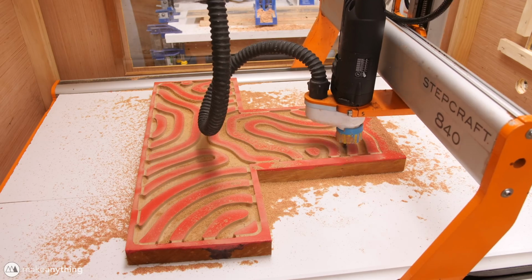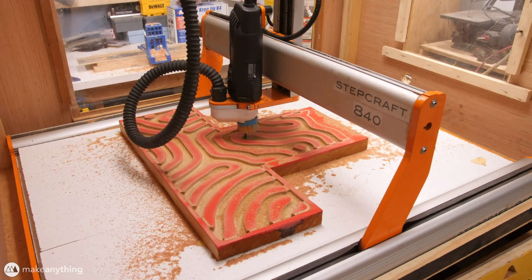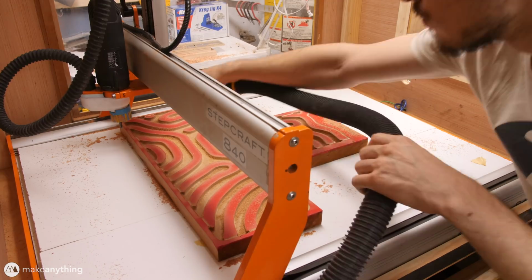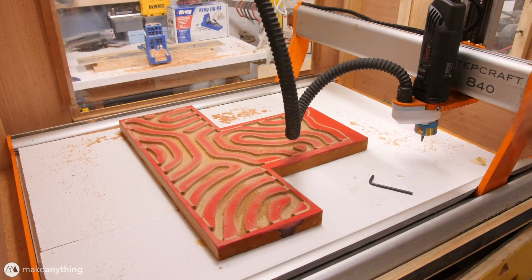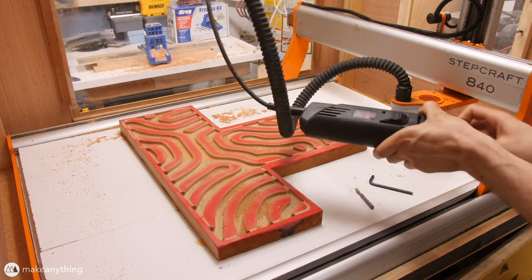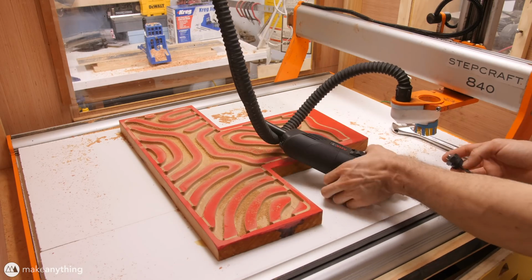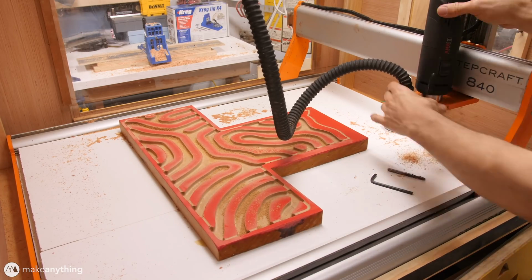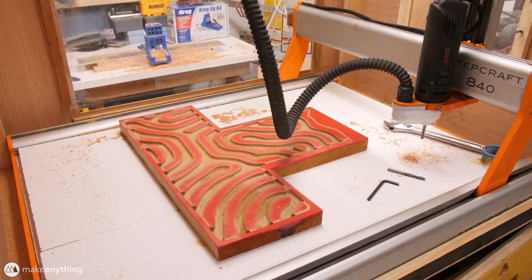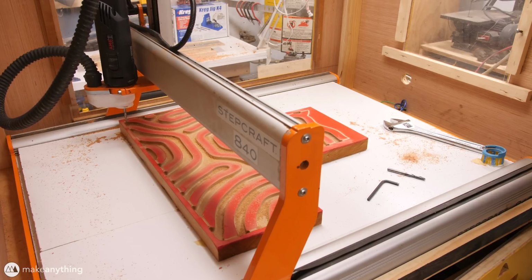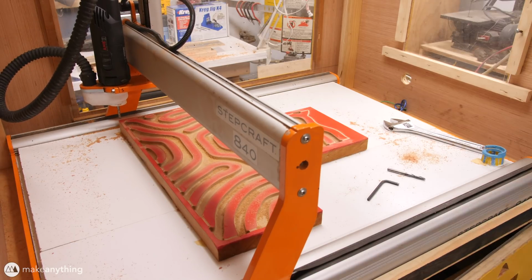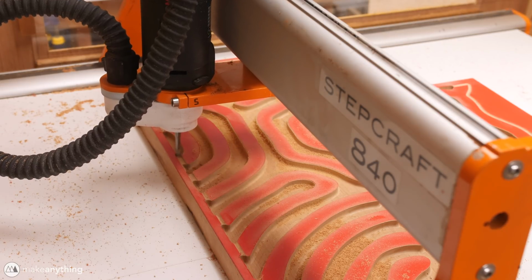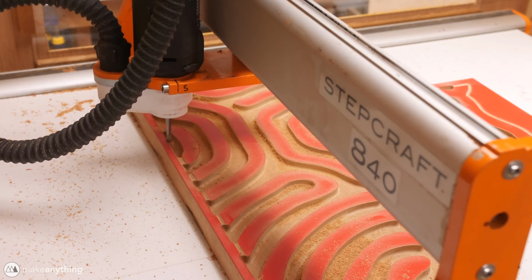Luckily, my Stepcraft 840 CNC completed all of the cuts with no problems. And then after a little bit of cleanup, I went ahead and switched out the tool bit manually. So I'm just gonna go ahead and pull it out, take out that flat end mill, replace it with the round end mill, and then make sure that the 0 position is still the same right in that corner. And then I'll run the second part of this operation, which is the 2-dimensional contour that cuts the entire outline